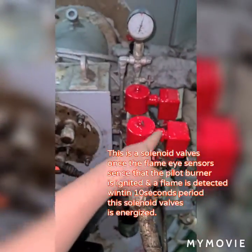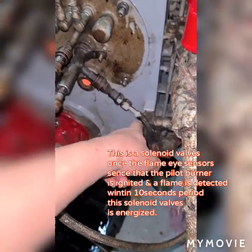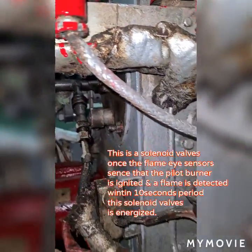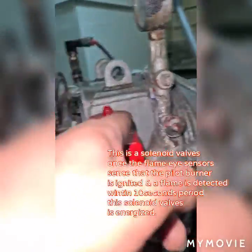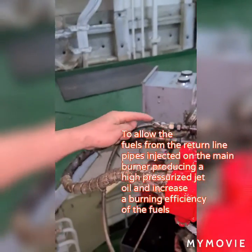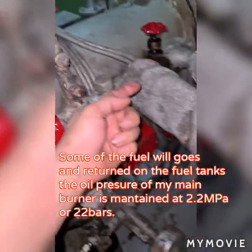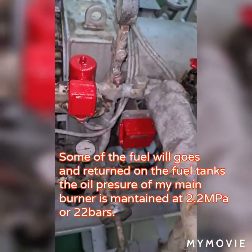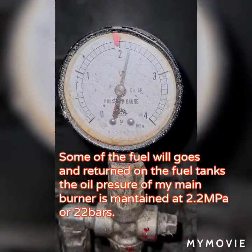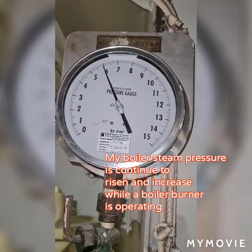This is the solenoid valve, which is open to allow a high-pressurized fuel jet to penetrate inside of the main burner. This is my return pipeline, from which some of the fuel goes to the main burner while this solenoid valve is energized, and some fuel will proceed and return to the tank. This is the pressure gauge of my fuel burner, having 2.2 megapascal or 22 bars.